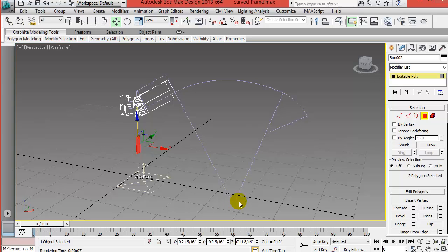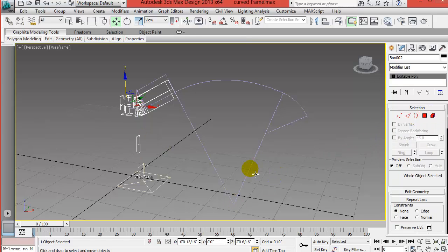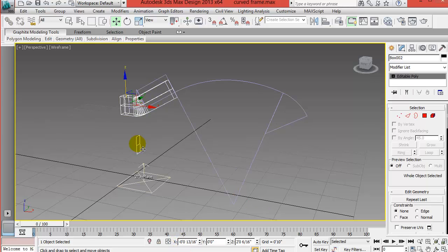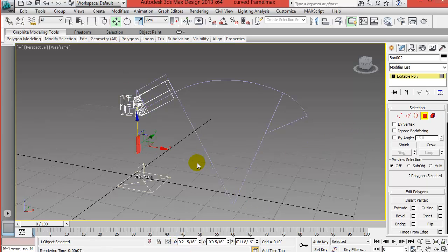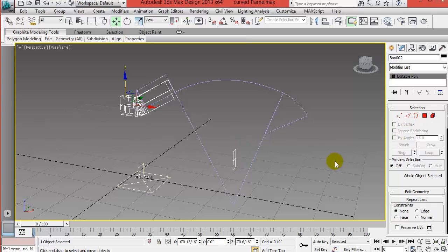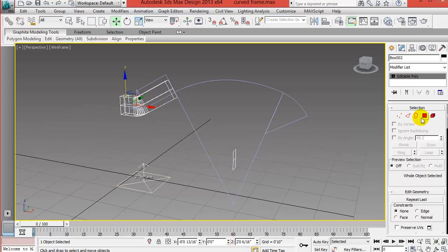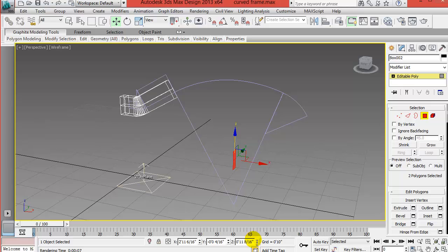Let me move this down here for now, and then we're going to copy the location of, or the parameters of the arc center, and we're going to paste it on the parameters of this polygons. So copy x, enter, copy z value, and same way we'll paste on this one here.